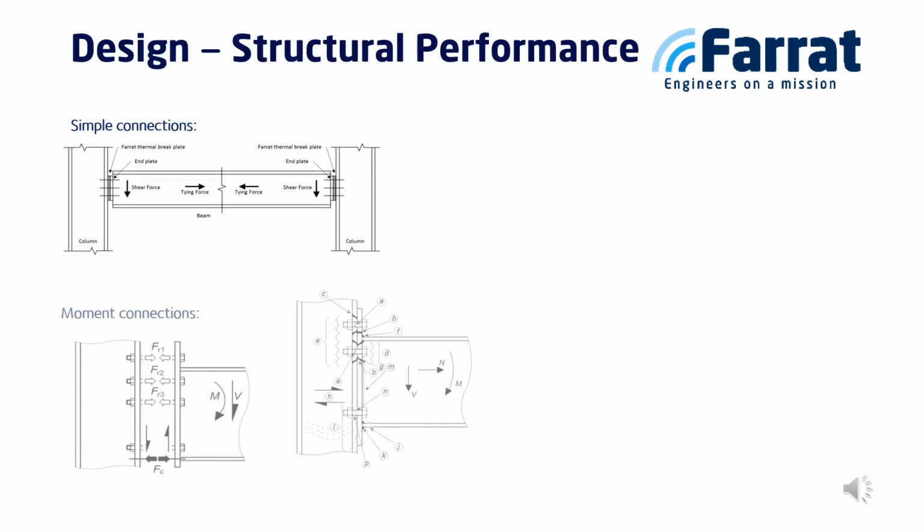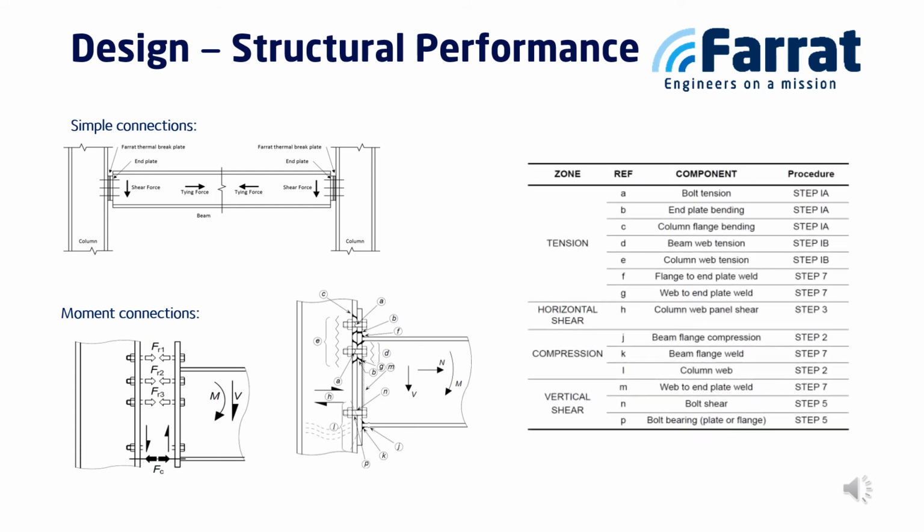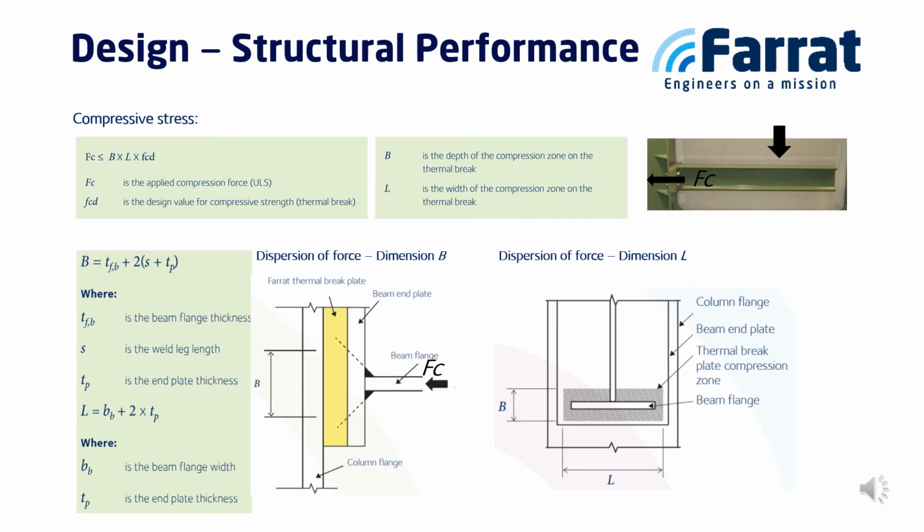Structural thermal breaks can be designed into any simple or moment connection. In steel connections, the introduction of the thermal break typically will not impact connection and member size, but will allow flexibility in achieving uncompromised details. As well as the simple evaluation of a compressive strength figure, account should also be taken of the material's ability to disperse loads from highly loaded points of a connection. This factor and the selected material's ability to deal with these loads should be addressed by the material manufacturer.